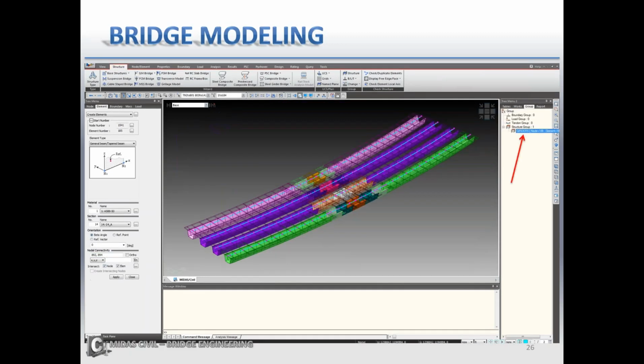You're also going to want to assign groups to all of your elements of your structure. It makes it a lot easier to work in the model because you can manipulate the model through these groups. So I clicked on the works tree and I highlighted the sections I want to group together. So say if you want to group all of the different elements for girder 1, you can go into the elements tree and display all of the sections you want to group. And once you click on girders, it'll have that assigned girder. So what you can do is when you click structure group and create the new group, you can click on it and drag it into your screen, and it'll basically be assigned to any nodes and elements that have been highlighted in the model.